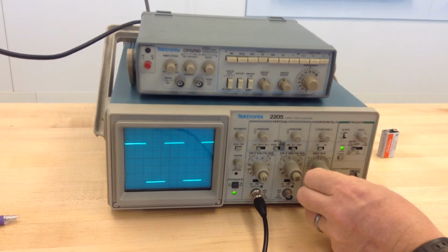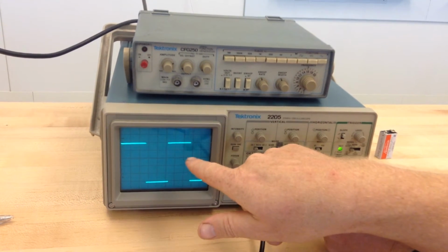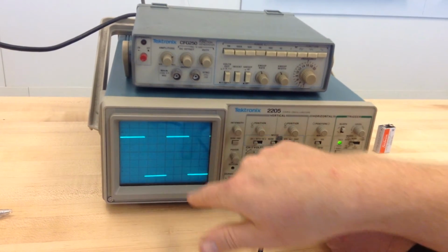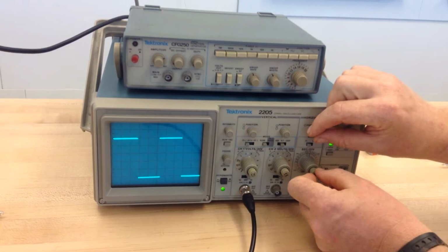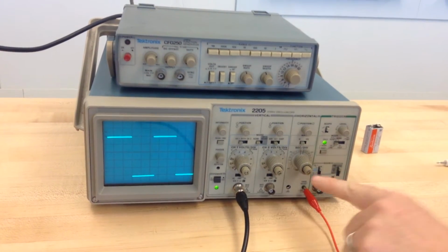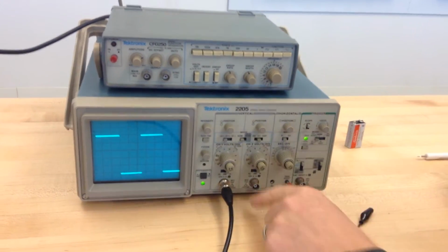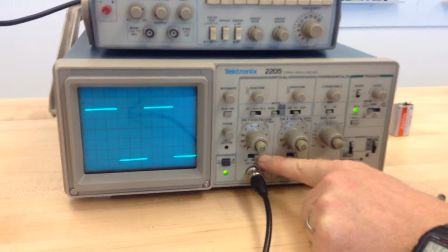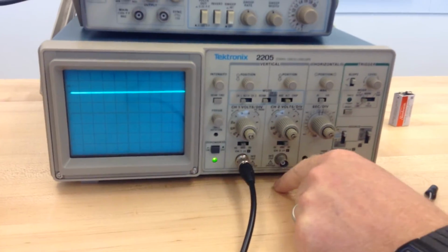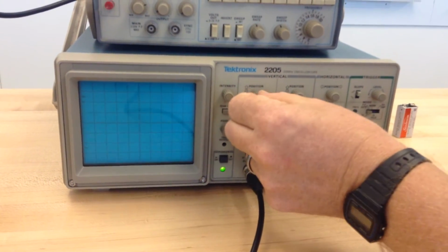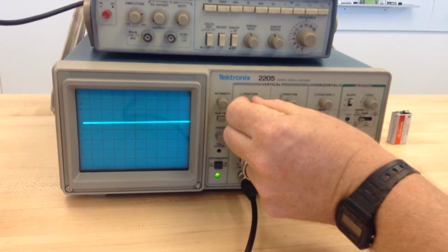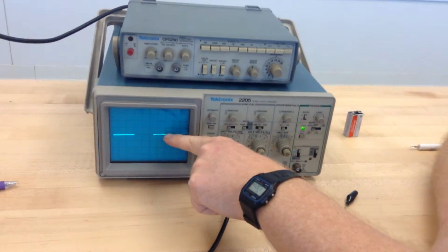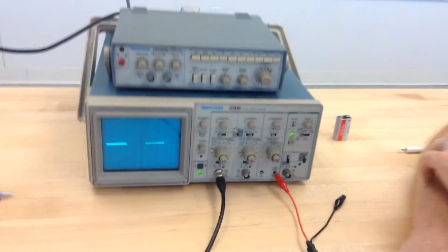So let's see, I've got to make this 5 divisions wide. I'm twisting this knob here, and I've just made it 1, 2, 3, 4, 5, a little bit off there. That's 5 divisions wide. I'm going to move it over to see. Good. So now it's calibrated. I don't touch these knobs anymore. Now there's something else you can do. It says DC here for the signal. That means measure the absolute voltage with respect to ground. And I can hit the ground. That's my 0 point there. So I know now that whenever the beam is on that line, that's where 0 is. Oh, so this was going from 0 to negative half a volt.